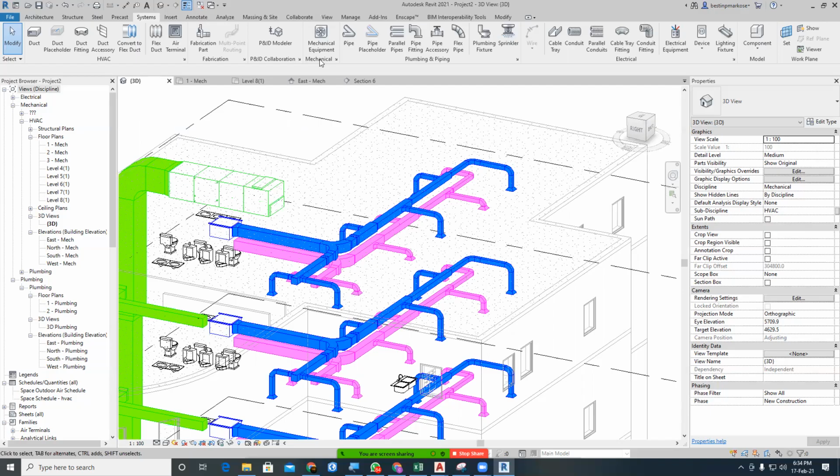Okay, what all concepts? How to create a new duct type. If it is duct, it is duct type. If it is pipe, it is pipe type. If it is cable tray, it is cable tray type. Then how to work with VG, how to create filters, what are view templates, how to duplicate views. So all those are concepts. The same thing will be repeated in all the other disciplines. Only the elements will be changing, right? So this is how you have to do it.